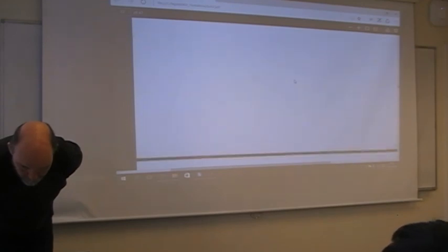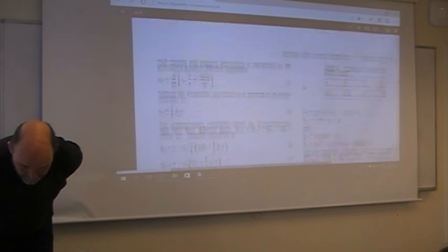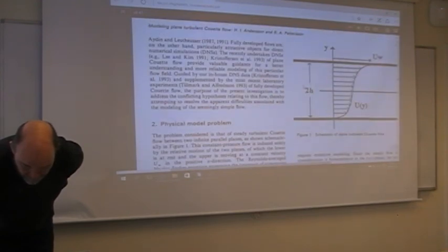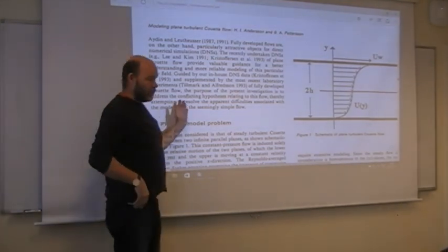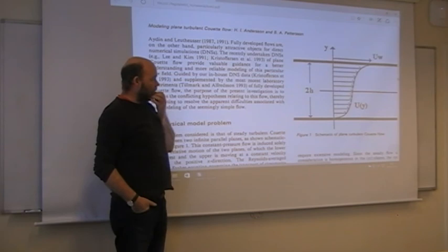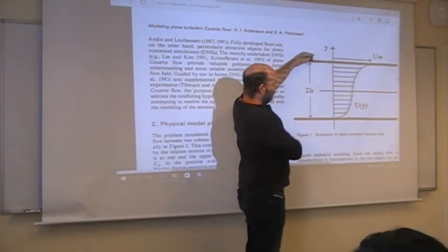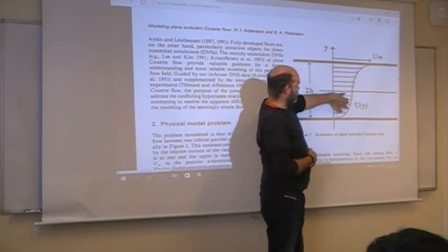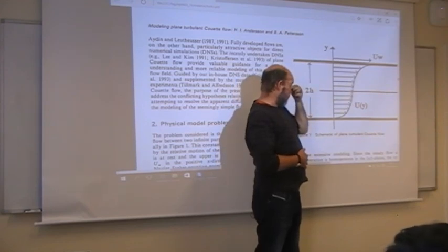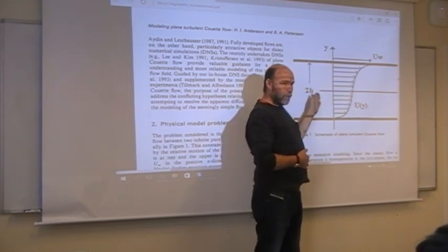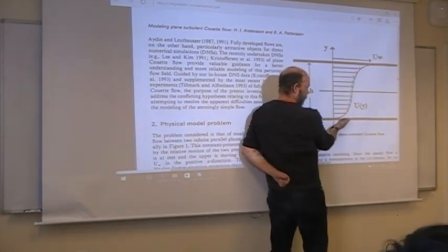Also, what you can see in the DNS simulation, that of course they didn't do in this two-dimensional simulation with the full Reynolds stress. So when you have this flow, you will, in this center region, and this is sort of what is interesting for a lot of turbulence modelers, if you increase the Reynolds number, these turbulent boundary layers are going to get sharper.